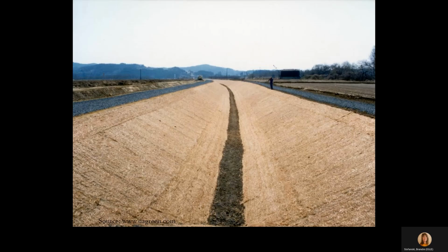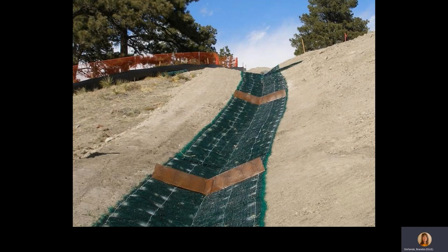Here's an actual installation. They did a great job. Here they ran along the top and trenched that in, then rolled down the slope along the channel. Here we see turf reinforcement mat and temporary check dams. This is a permanent control measure for vegetative growth. Once grass is established, it is comparable to 36 inches of riprap.